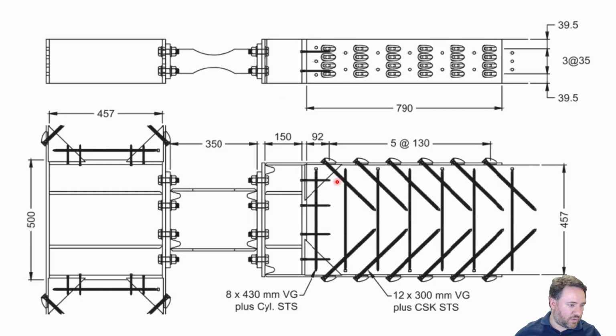And so we also looked at, and this came up in a previous live session, for these kind of connections, we installed some additional self-tapping screws. These vertical lines are long self-tapping screws. We installed them vertically throughout the connection to reinforce for tension perpendicular to grain stress. So it's kind of holding the piece of wood together so it avoids splitting. And this all worked very well.